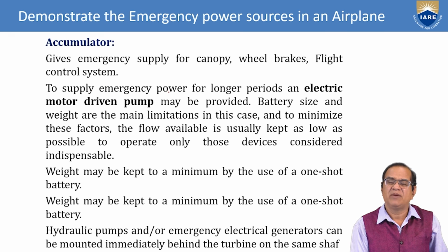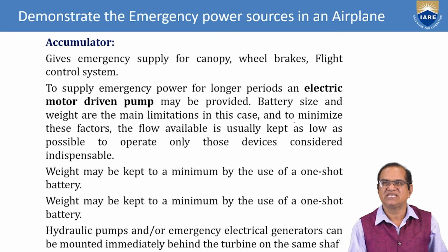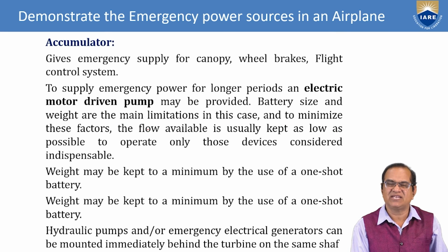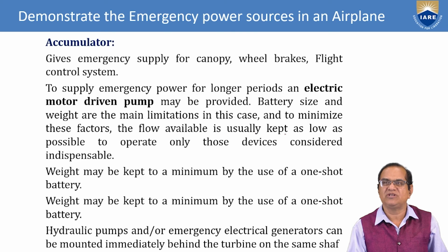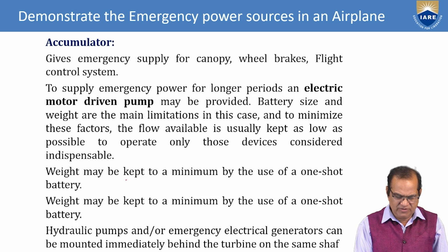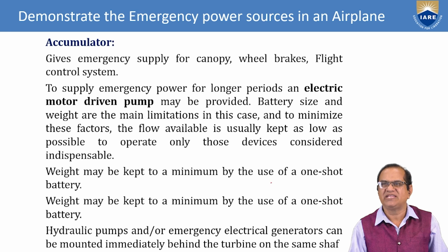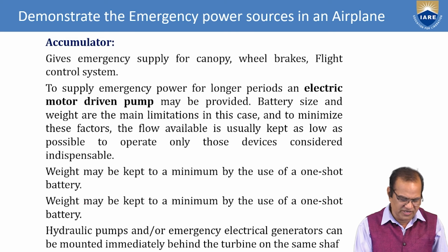To supply emergency power for a longer period, an electric motor driven pump may be provided. Battery size and weight are the main limitations in this case, and to minimize these factors, the flow available is usually kept as low as possible to operate only those devices considered indispensable. Weight may be kept to a minimum by the use of a one-shot battery.